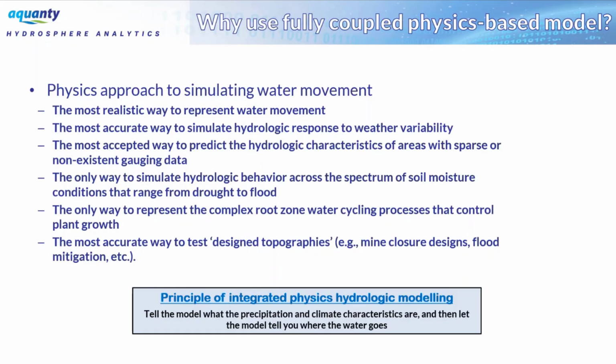Most surface water and groundwater models require a lot of consideration for the boundary conditions and the mathematical forcing functions that are used to define how the flow system works. But ultimately, if you are allowing physics to do all the heavy lifting and you're working with a fully integrated model, your forcing function just ends up being precipitation, at which point you should just let the model try and replicate the surface water flow system, for example.